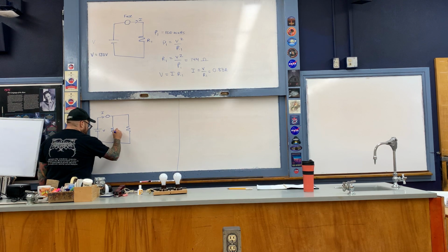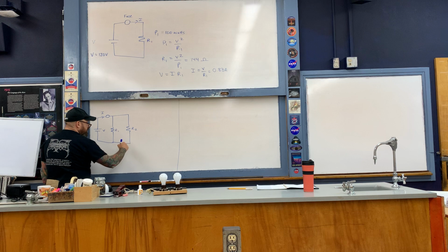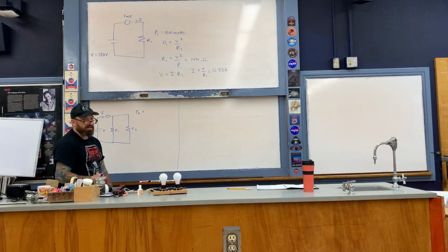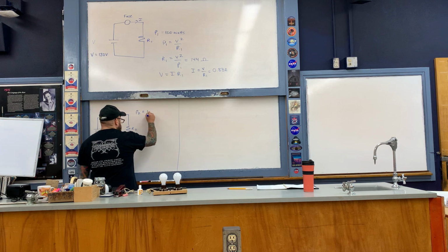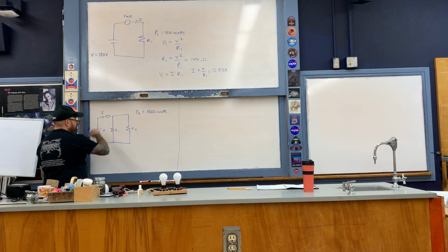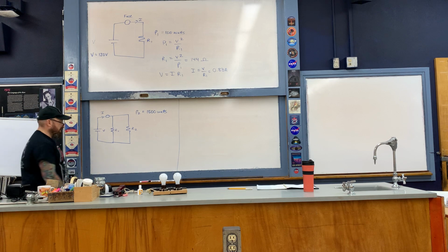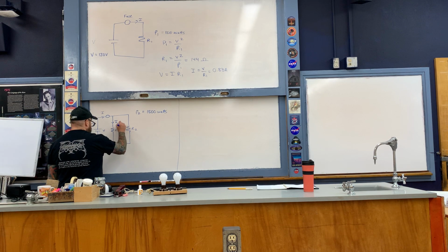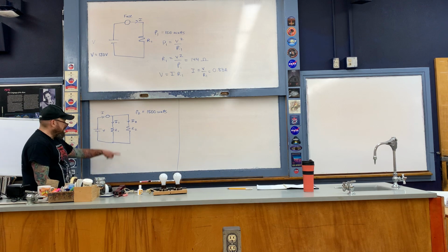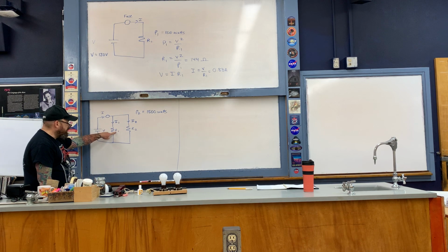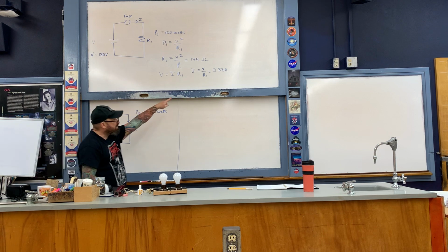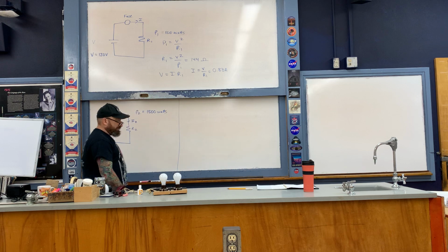Now we've got R1 from earlier, and now R2, where the power delivered to the electric space heater, P2, is 1800 watts. Here's the current I, and then we get the junction rule again. We're going to have an I1 flowing like so, and an I2 flowing like so. The I1 flowing through the 100 watt light bulb is exactly the same as we calculated earlier. It's 0.83 amps.